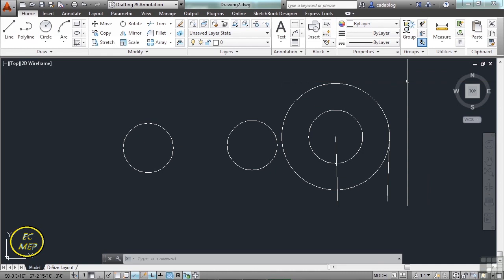You'll find situations similar to this while you're drafting. You won't always have just the radius. You won't know where the center point is. You won't know where the end point is. You'll need to draw a circle in a different way. Well, that's good, because you can. There are other ways to draw circles inside AutoCAD besides using the center and radius or center and diameter. Those other methods are drawing a circle by 3 points about the circle. Another one is by drawing 2 points about the circle. And then the third option that you will have here in this list is drawing at 2 tangent points and a radius. Say, well, how will I know when to use what? Well, that's great. We'll look at an example.